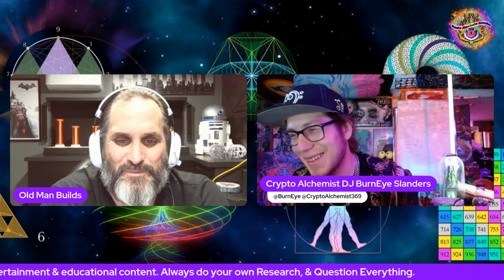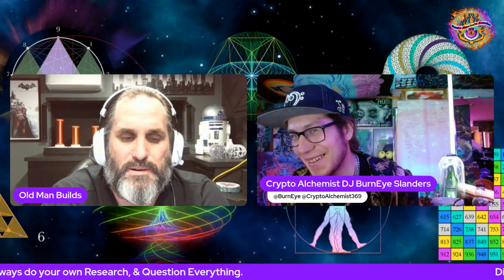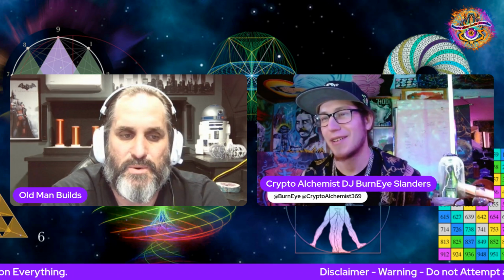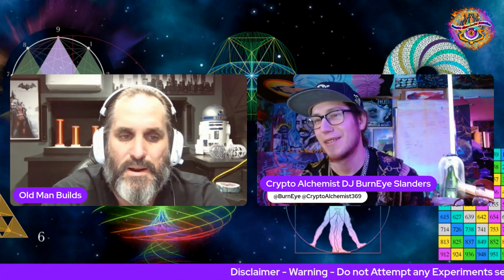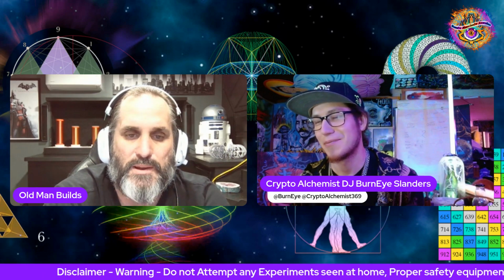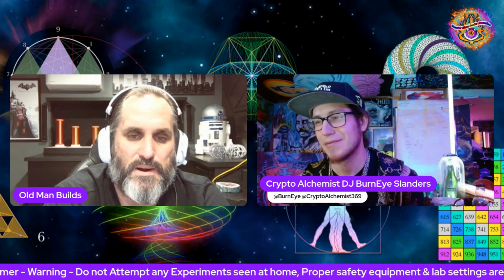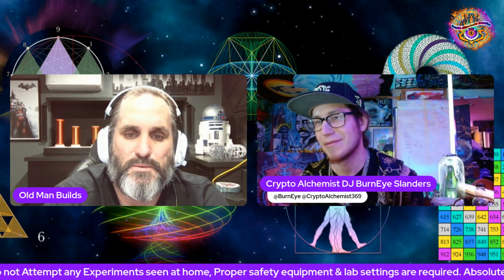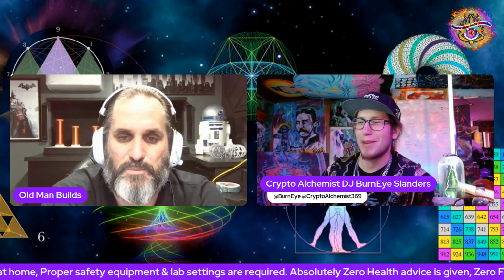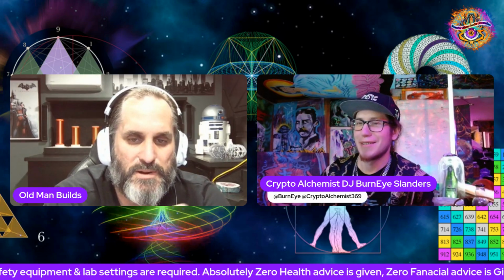What equipment do I need to get to be doing that next? Basically, Bernie, a Slayer Exciter. Test the coil, build the negative one that I do. It's one transistor, it's one resistor, and that's the whole thing. You can run it up to 40 volts, and it'll run all day long cool. It will not blow up on you. You probably only want to run it at 5 volts or something like that for what you're doing.